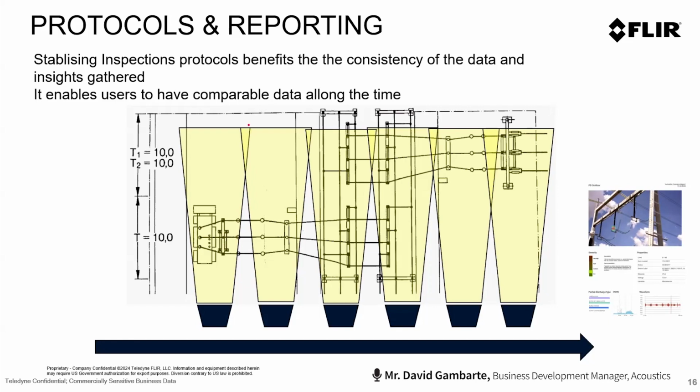You find new ones, you take a snapshot. If you find old ones, you also take a snapshot. So basically, along the time, you will be able to see the evolution of the partial discharges that exist there. Some of them might be mild. Many of the partial discharges are not critical, but it's worth following them up because you can take actions on them when you see that, for example, the severity level is increasing.